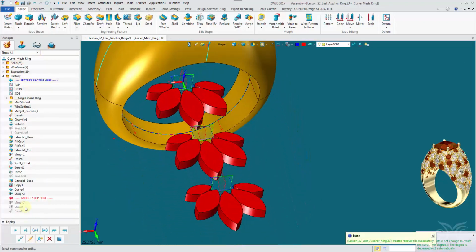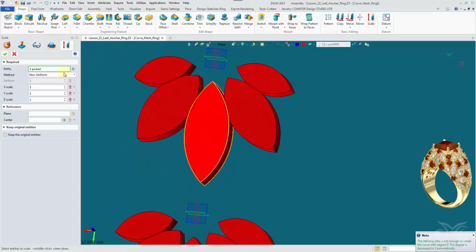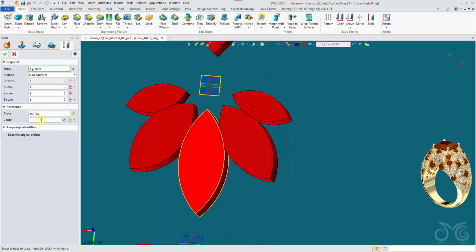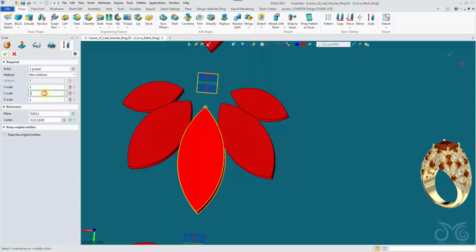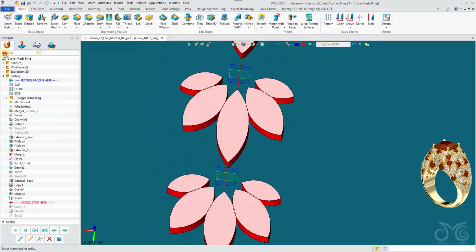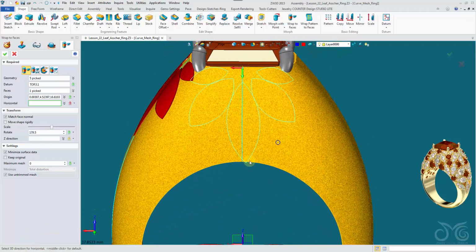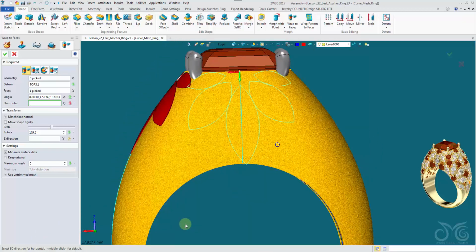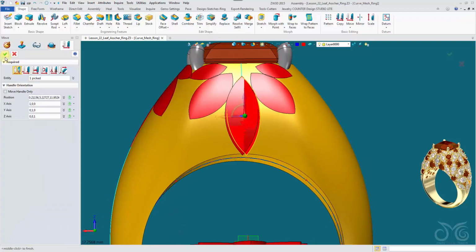So before I edit morph 3, I'm going to scale this leaf non-uniformly, plane, center, pick the center at the end point. I just want to scale slightly in the Y. That's probably enough. Edit the morph. Okay, you can see how I've brought it down now. Confirm that. See if the move is going to update it nicely.